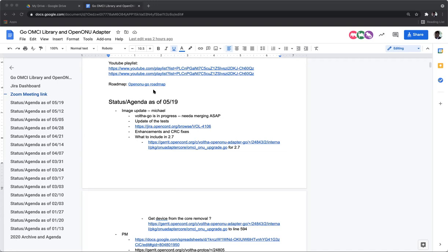Well, thanks to Amit and Simon and their tests, and on the other side, we also made some tests in some Adtran pod. We could verify that the CRC that we provided so far on the OMCI for the end of the software download was not correct. Investigating that in more detail proved that the CRC byte sequence was simply reversed compared to what it should be.